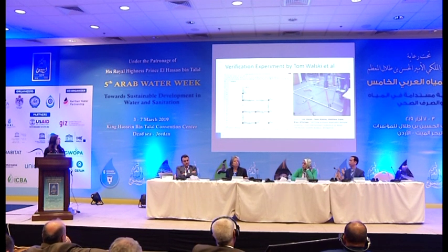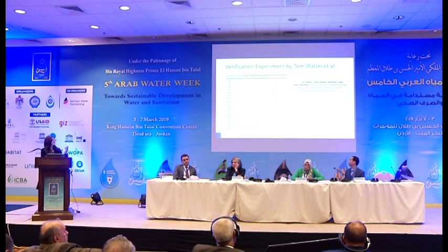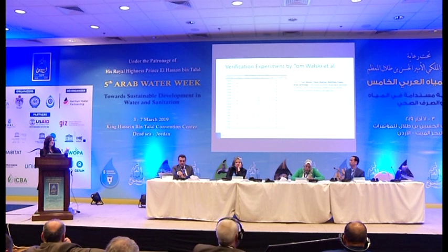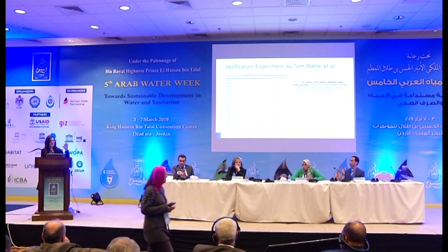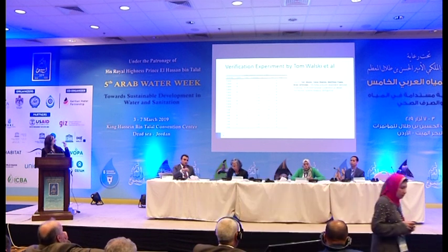They did 12 combinations using the S-shape model or the grid, either turning the valve at outlet B on and closing the valve at outlet C, and so on. With those different combinations, they compared the pressure and flow at outlets B and C to the results of a hydraulic model that simulates the same experimental conditions using pressure-dependent demand analysis, and they approached similar values between the theoretical results and the experimental results.